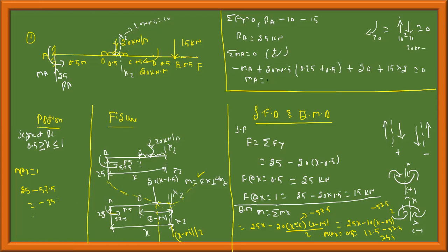Okay. Now, in order to practice, this is very simple. Once you understood, this is very simple. Next step you will understand. There is little constraint for space, that's why it has become jumbled. So, in order to plot this shear force, there is a x term in the shear force. Shear force is of magnitude 25 kilonewton. Load is constant here. Load was 0. Load is constant here. Therefore, shear force should be linear.